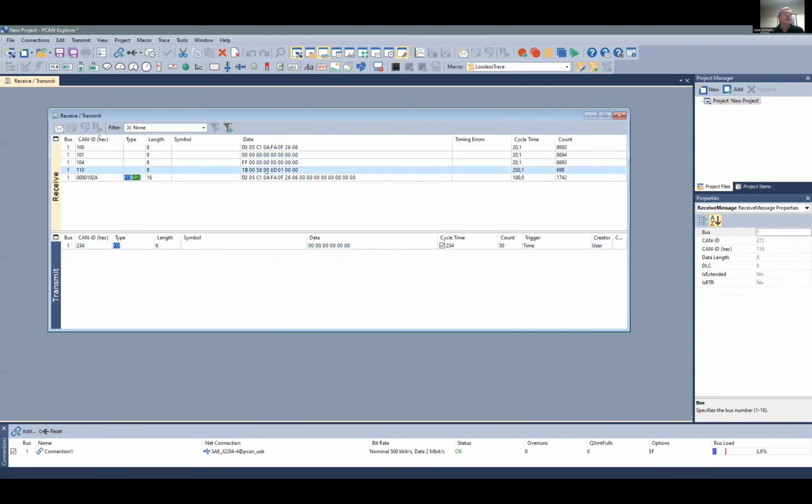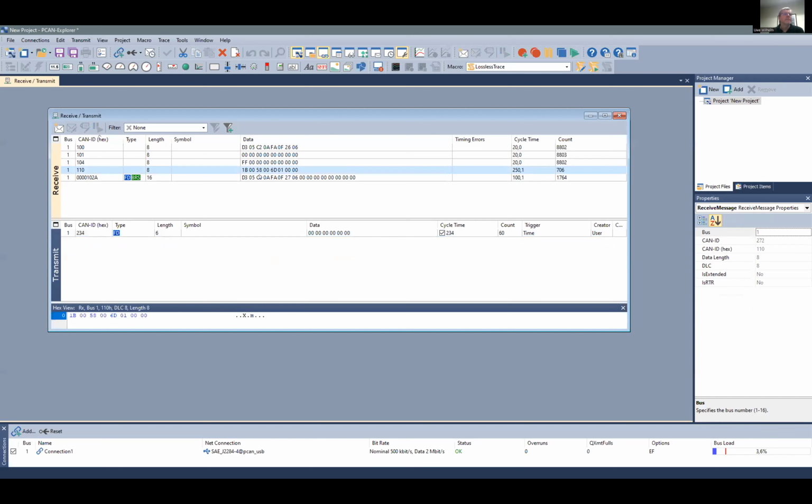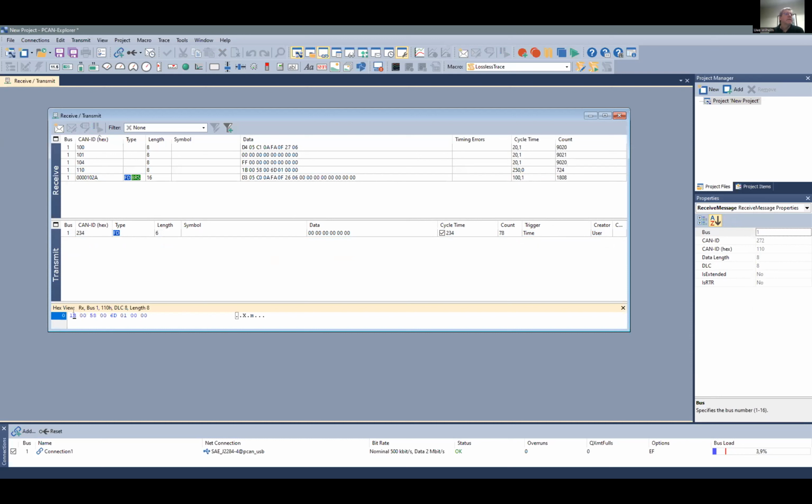But as you see in a moment, everything is in hex. You can simply select one, and then you see it also in ASCII, but it's in a nearly unreadable format. For that, we can implement a database type, which we call symbol files. Symbol files are only a description of how the CAN data in the data part will be decoded by the software itself. There are other standards, for example, the CANDB standard from the company Vector, which also includes a database.